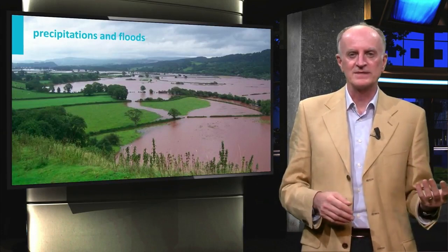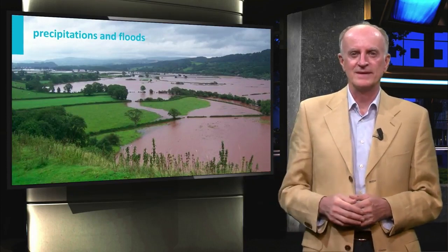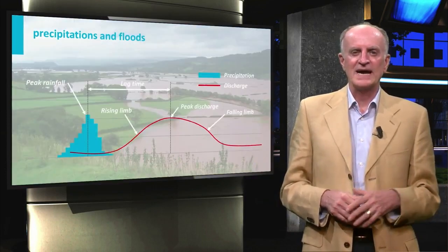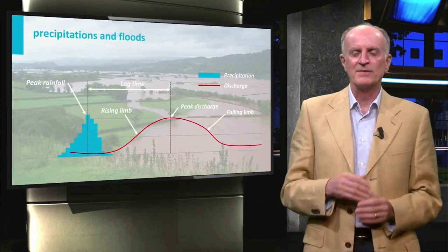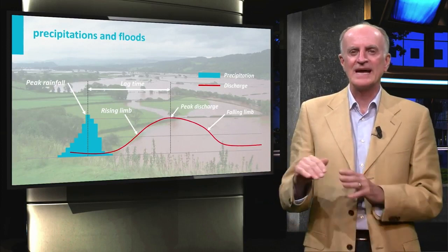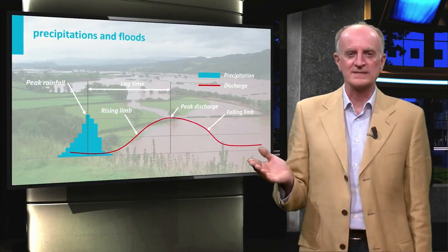These are typically associated with increased precipitation on the mountains and possibly with difficulty in discharging waters to the sea. Floodplains are typically far away from the mountains, and the increased water volumes generated by high precipitation in the mountains arrive with a significant delay, but also last stronger and longer, in the order of weeks.